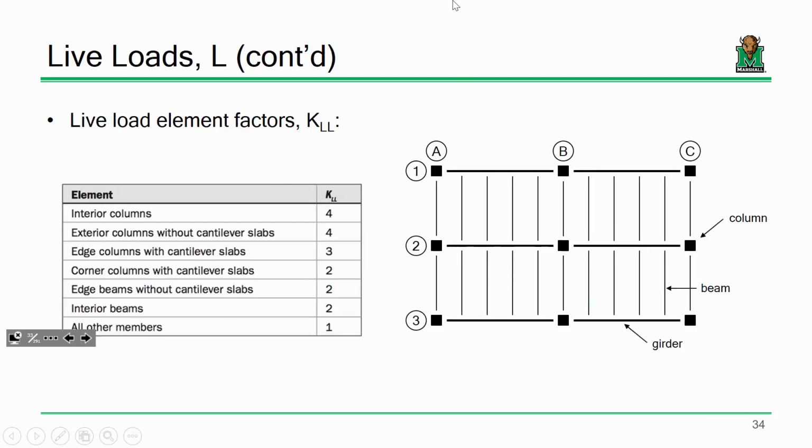All right. The only thing that's new is this live load element factor, and it's pretty straightforward when you think about it. I actually want to draw this out and show you a couple things. So I want to look at a typical floor beam. Would you agree that the tributary area for that floor beam looks something about like this? Make sense? Okay, this is the tributary area. All right? Now, tributary area is halfway over to the next adjacent element.